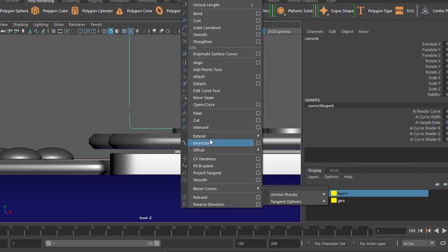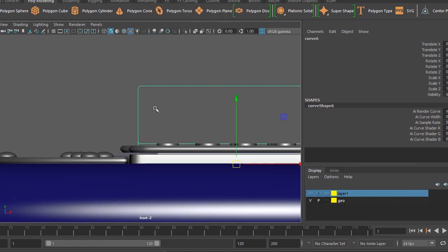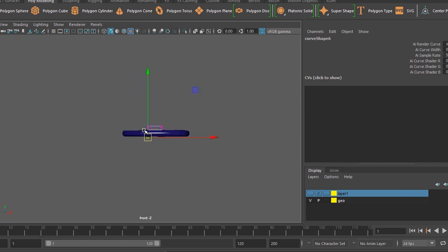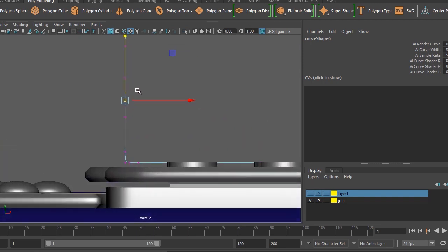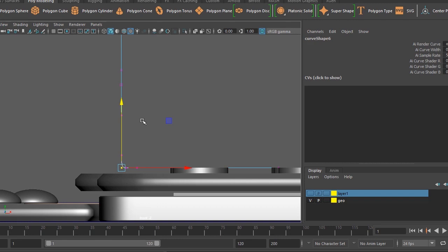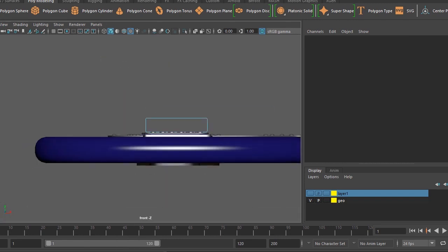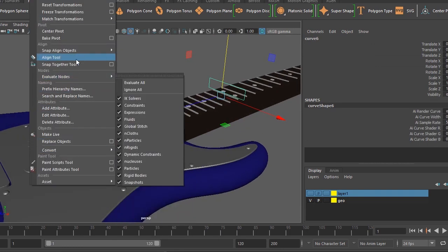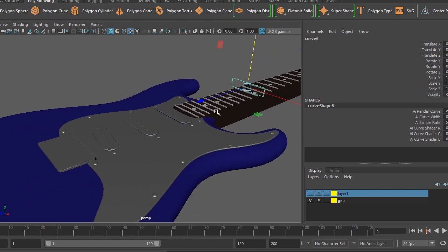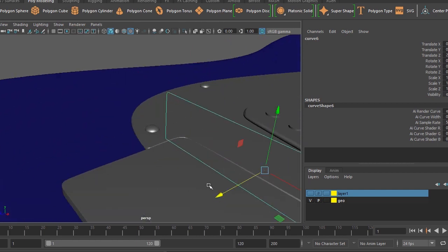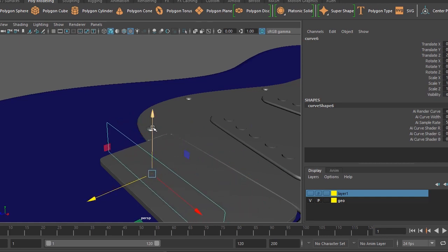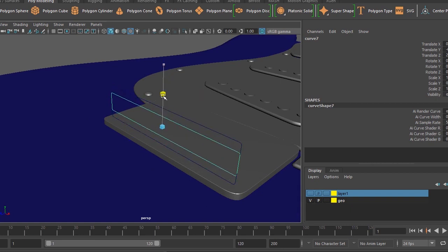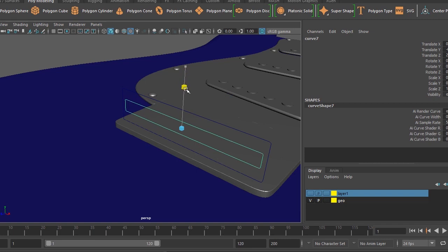Use this tool called open close curve, and then select the point, and then so I've got this option here, modify center pivot. So the pivot point comes to the center. I'll put that here and then just insert it, Control D, and then scale it like that.